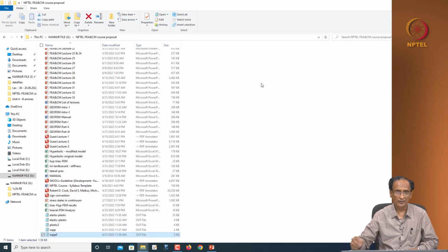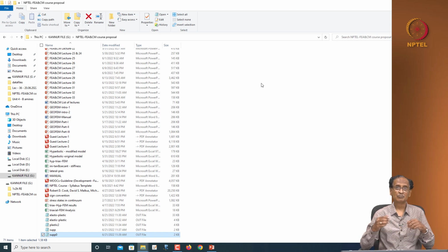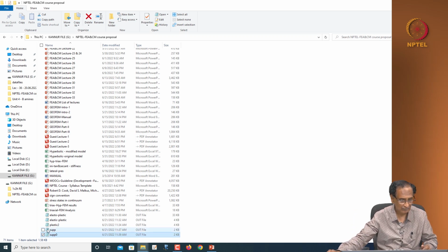So, with this type of model we can simulate the volume expansion, and if you prevent the volume expansion you get higher stresses, similar to the swelling of the soil. If you allow the soil to swell freely, there will not be any swell pressure, but if you prevent the swelling from happening, then you get the swell pressure. The same thing happens even with the dilation, and this suppressed dilatancy can increase our shear strength. That is what we have seen here.